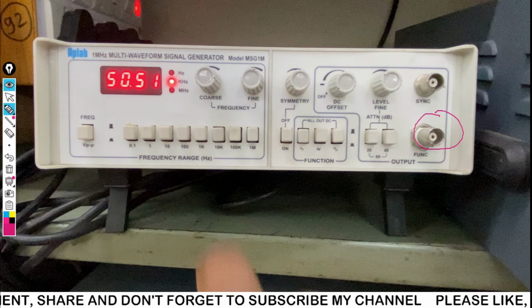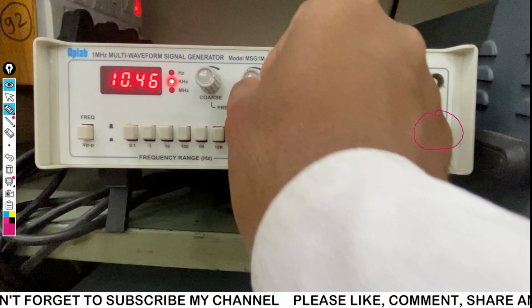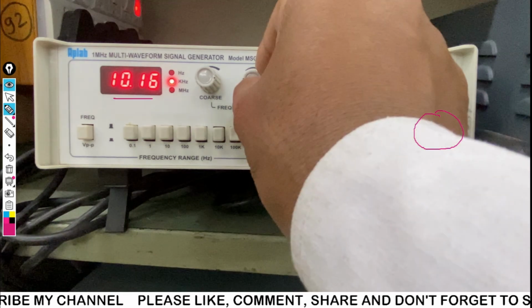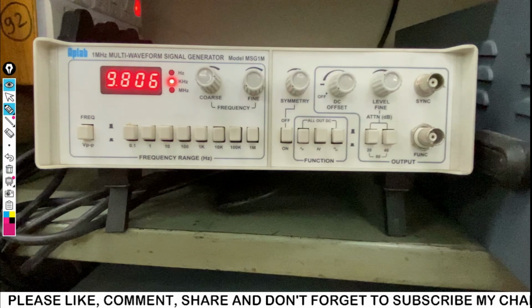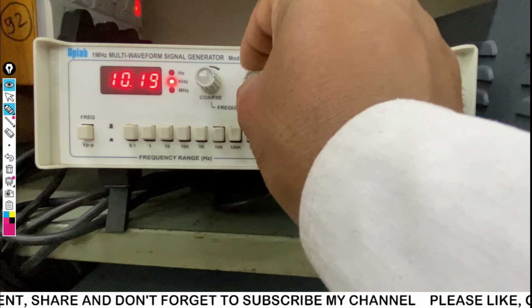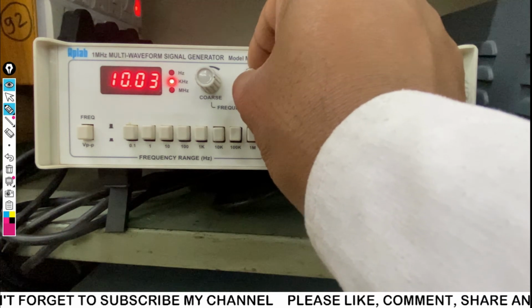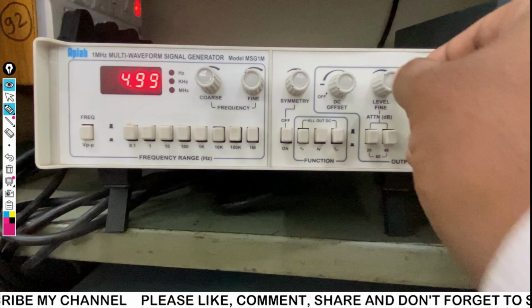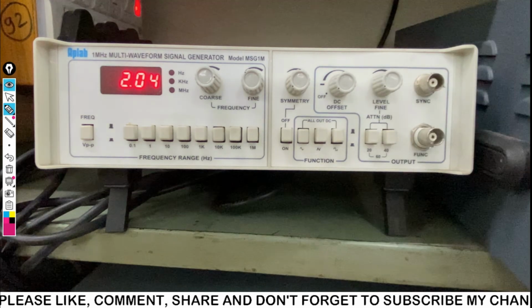If we have to change the frequency, we can press the other button, using coarse and fine. We keep the fine button at middle, and using coarse and fine we adjust the frequency to 10 kilo. The voltage is 5, and I am adjusting the frequency towards 10 kilohertz. This particular AppLab function generator's response is very slow, so we have to change the knob and wait for the result to become stable. You can see I have adjusted 10, and now it is 4.99. I'm adjusting it to 5. In this way we can have 10 kilohertz and 5 volt.